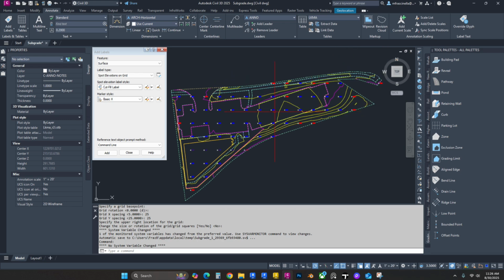And that's it. So that is the easiest way, at least that I know of, to create a subgrade. It's going to give you a very accurate calculation for earthwork. And it's a pretty easy, simple process. Regardless of how big the site is, it's still the same thing. It's just polylines with elevations used to create a surface, some comparison surfaces, and then boom, you got your subgrade.